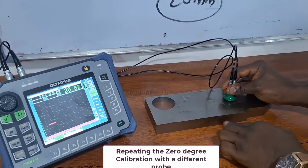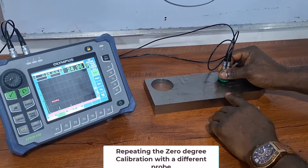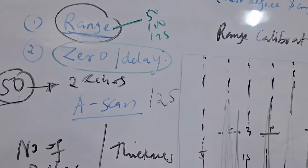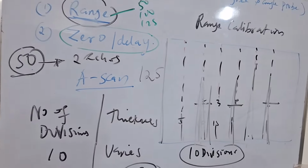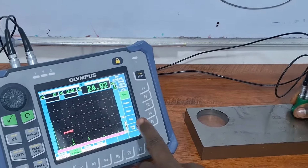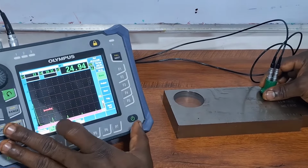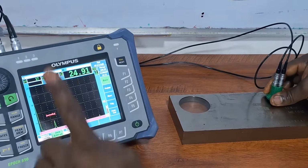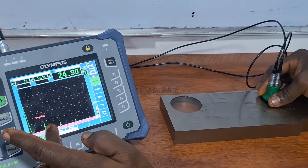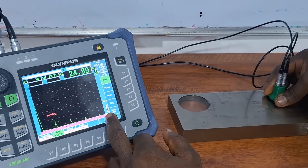So with this thickness that we have, we know that this thickness is 25 mm, and then we are taking a range of 100. And if we are taking a range of 100 and we divide 100 by 10 divisions, it means that each division should be 10. So if we are going to take a range of 100, it means we are going to get 4 echoes. One should be at 25, the other one should be at 50, the other one 75 and 100, just like that. So I'm supposed to get one between 2 and 3, and of course this is the last one, 100, I should be getting an echo. This is almost where it should be.